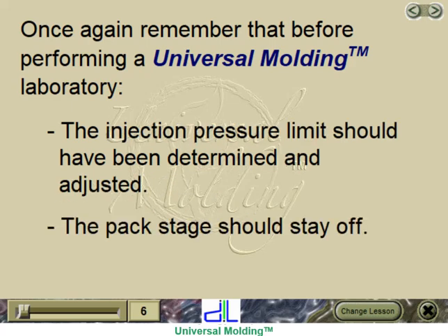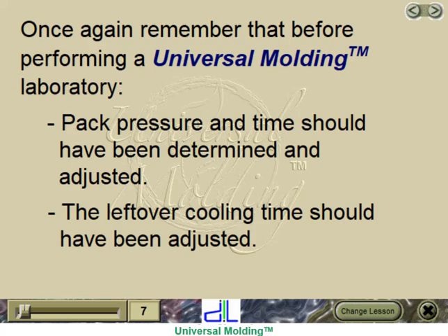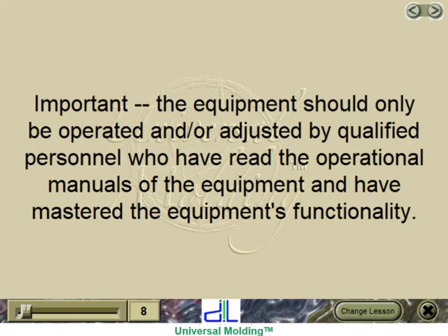The pack stage should stay off. Pack pressure and time should have been determined and adjusted. The leftover cooling time should have been adjusted. Important: the equipment should only be operated and/or adjusted by qualified personnel who have read the operational manuals of the equipment and have mastered the equipment's functionality.